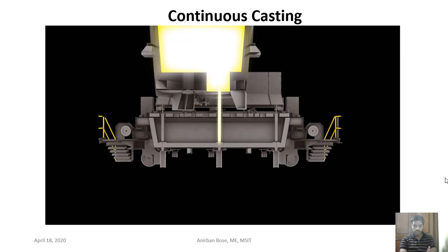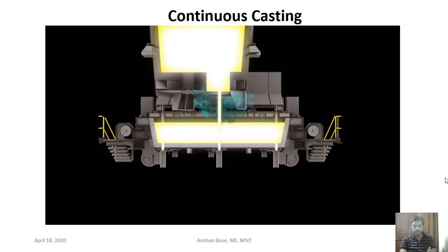ladle into the tundish. During this process, a physical shroud and inert gas protect the steel stream from oxidation. As steel flows through the tundish, a series of flow modifiers control the flow, allowing for optimum inclusion flotation and steel cleanness. The steel then exits the tundish to each of the 3 strands. We use refractory stopper rods to control flow from tundish to mold.